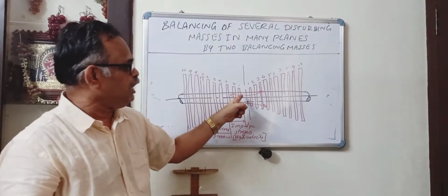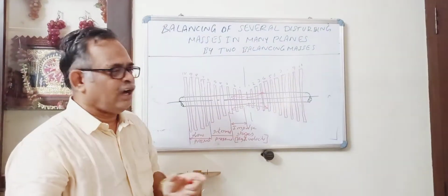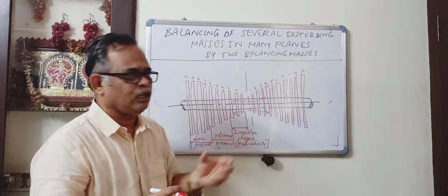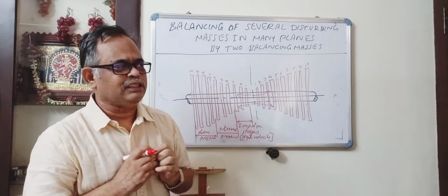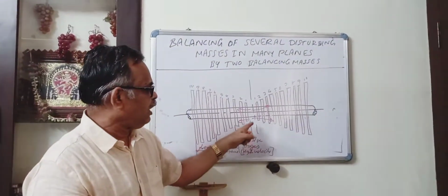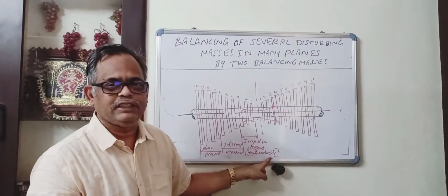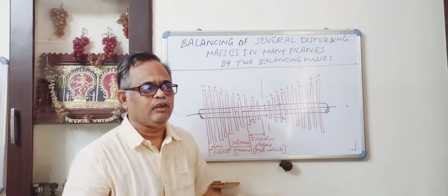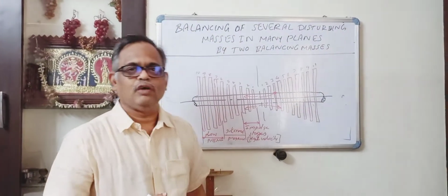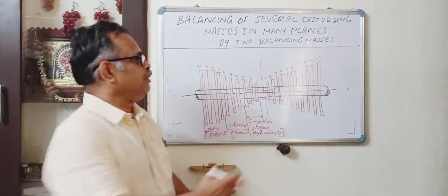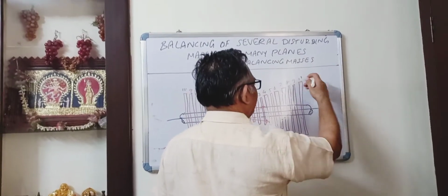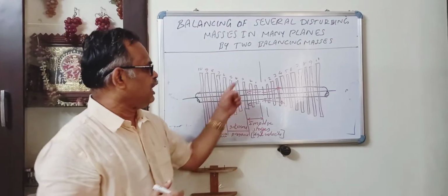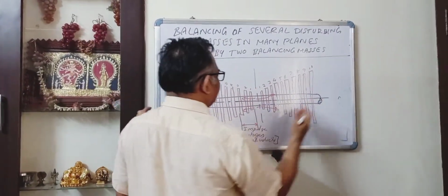Here, high pressure steam will be injected, and as it comes out of the jet of the nozzle, all the high pressure will be converted to very high velocity. So it will come as high velocity steam at this end, and as it goes on, the steam velocity will keep reducing. At the same time, pressure also will be reducing, right? Because at this end it will be connected to a vacuum pump that will pull the steam through the condenser, right? So like this, there are so many stages, right?